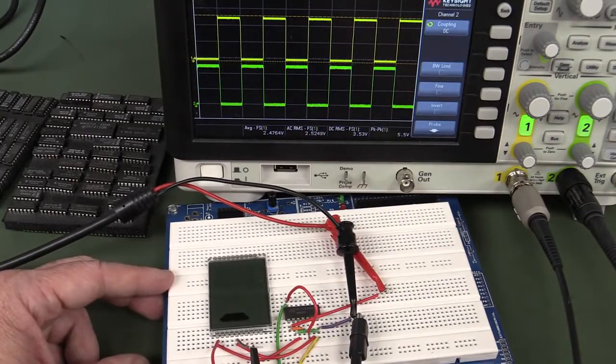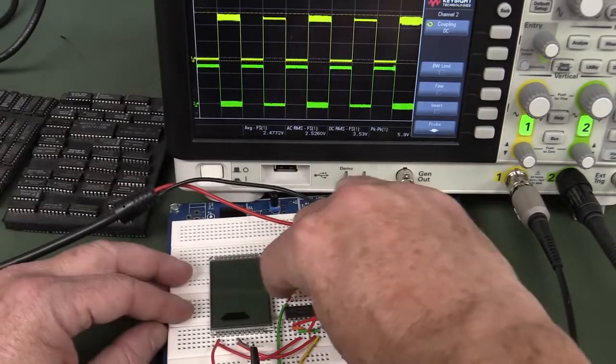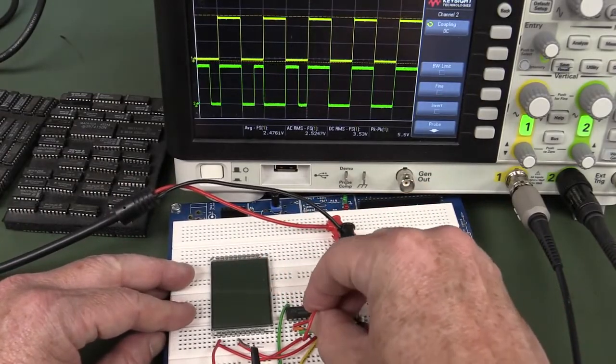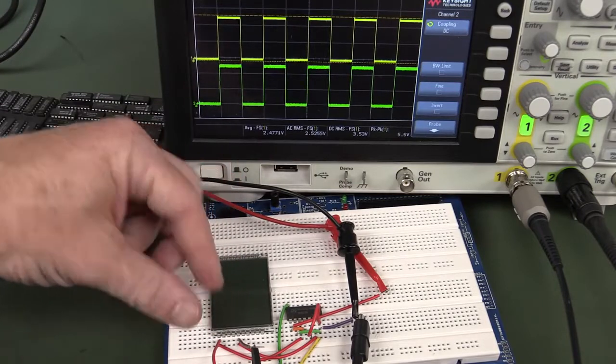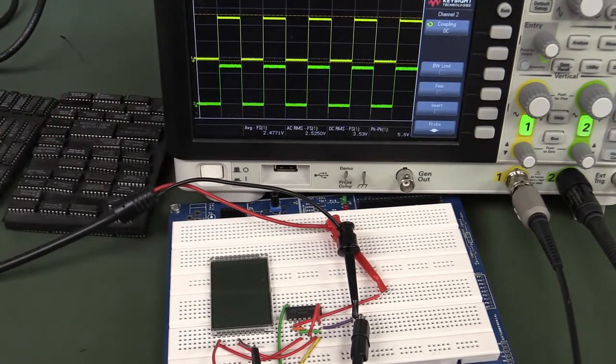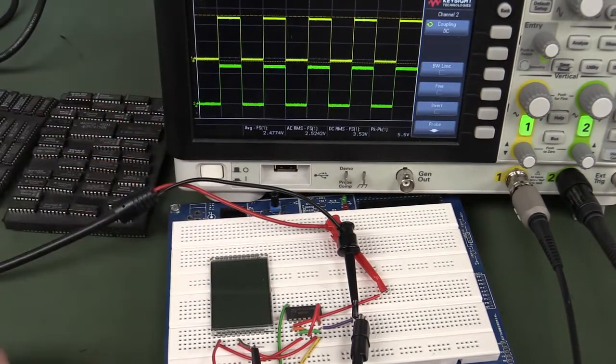Anyway, if you hook it up to a 1 there, it inverts the phase, segment turns on. You connect it to ground, there's no inversion in the phase, it's the same signal, the pins are effectively tied together, segment turns off. That's it. That's how you properly drive a static LCD with a TTL signal.